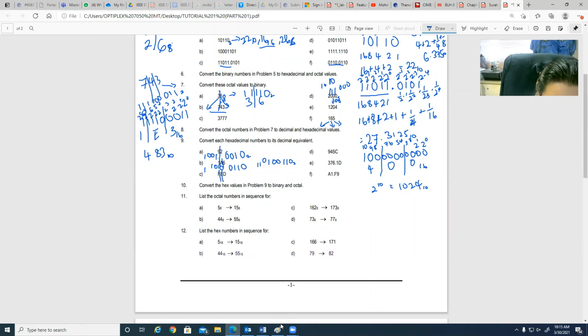Similar like this one, D in 4 bits is for example 1101. And then for E, 1110, and then for F, 1111. You can convert and then combine, so this is the answer. Similarly, you can split and divide by 4 bits each. For 9 change to binary, and then for 4 change to binary, and then for 5 change to binary, and C change to binary, then combine. So that is for hexadecimal converted into decimal.